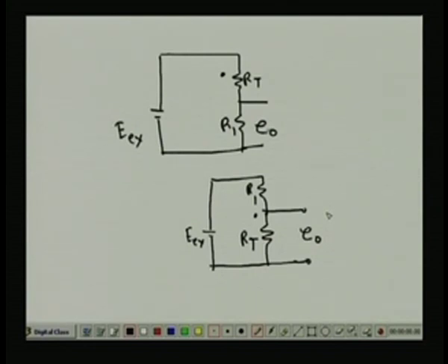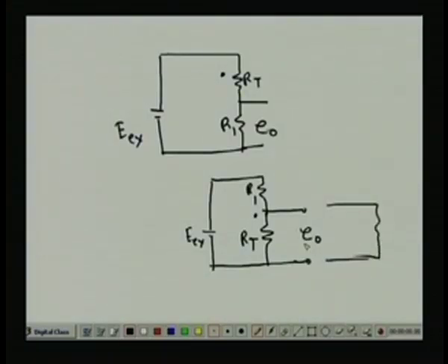In some cases it will have some value, in some other cases another. So, it will make a problem in the subsequent signal conditioning circuit. That means, if you have signal conditioning circuitry here, then designing that type of circuit will be different. Whereas, if you make the circuit like this one, I will always get the same impedance R1, right. So, that is the reason instead of connecting like that, I put the thermistor here. So, this circuit should not be used. We should use this circuit.